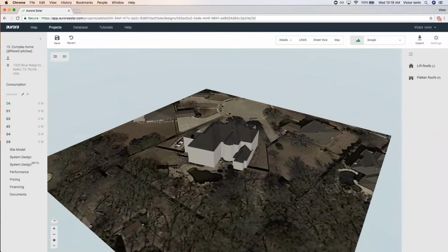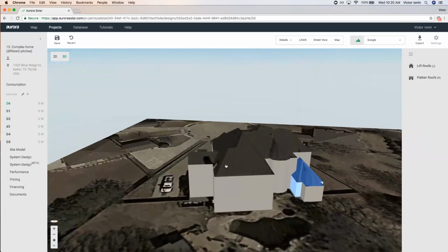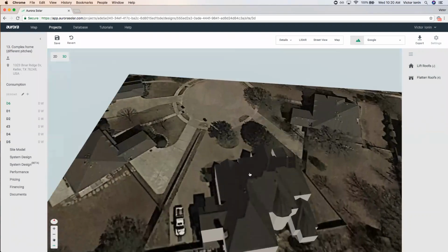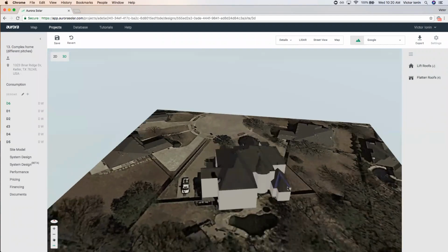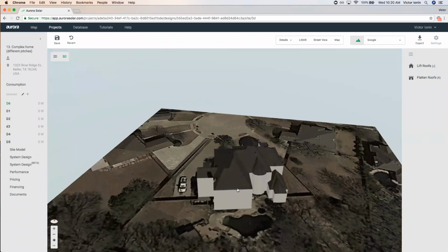All right, let's just go ahead and jump into your examples. Do you guys have any questions about this? So pretty much for modifying the interior edge lines, I recommend doing the more basic steps, which is pitching and unpitching of roofs, maybe breaking the structure apart into bite-sized pieces. Now I drew this entire thing as one piece. Now you could probably break this down into multiple pieces if it's a little easier. That might make it more manageable. But I drew the majority of this as one outline.